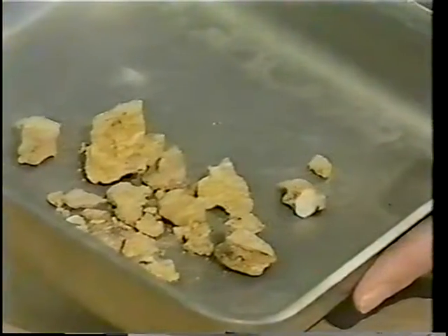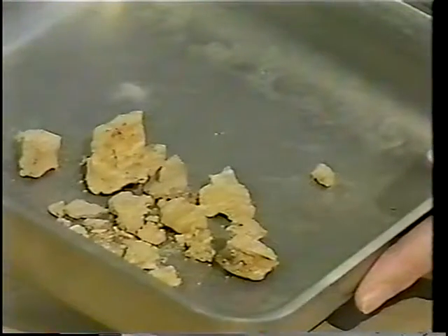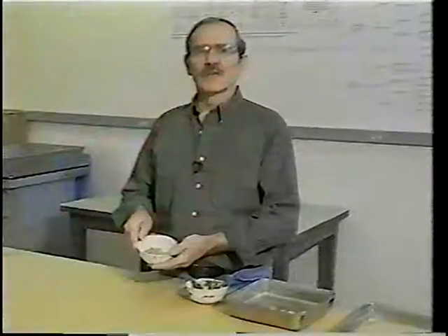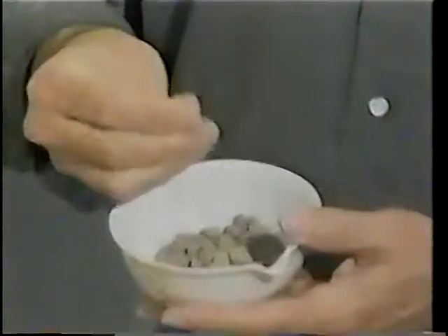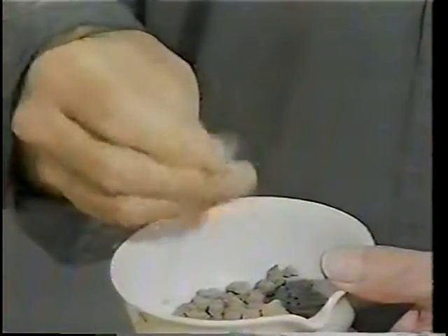Clays and silts provide the least support for pipe, especially when they're not compacted. Clay forms hard clods when dry, and it's soft and sticky when wet. Silts are non-plastic or have low plasticity. Lumps of silt can be broken easily and feel like flour. Clays and silts are difficult to compact when too wet or too dry, and are often troublesome to work with.